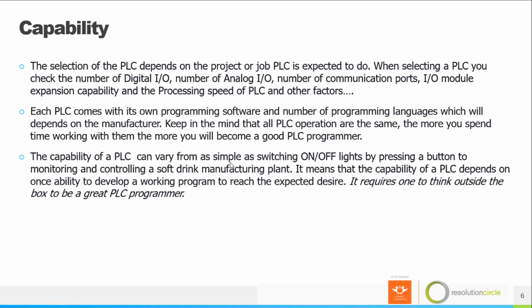When it comes to the selection of a PLC, it depends on the project or the job that the PLC is expected to do. When selecting a PLC, you must check your digital I/O, which is the number of your digital inputs and outputs, the number of analog inputs or outputs, the number of communication ports, and whether that particular PLC is capable of expanding your IO modules.